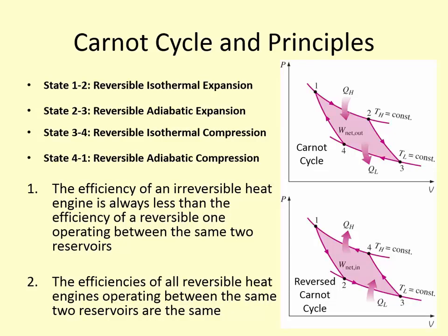And we can use this in a couple of ways. One, it's to see whether or not our system is performing as well as it could be, by comparing it to the theoretical max. The other nice bit is that we can look at the efficiency we're calculating for some designed system, and if it's somehow greater than this Carnot efficiency, then we've done something wrong. Okay, so there's something incorrect in our calculations, and we're actually designing a system that isn't possible to exist in real life.